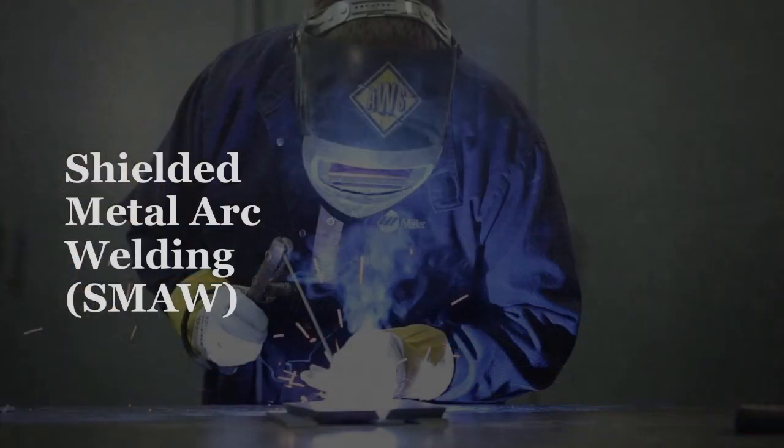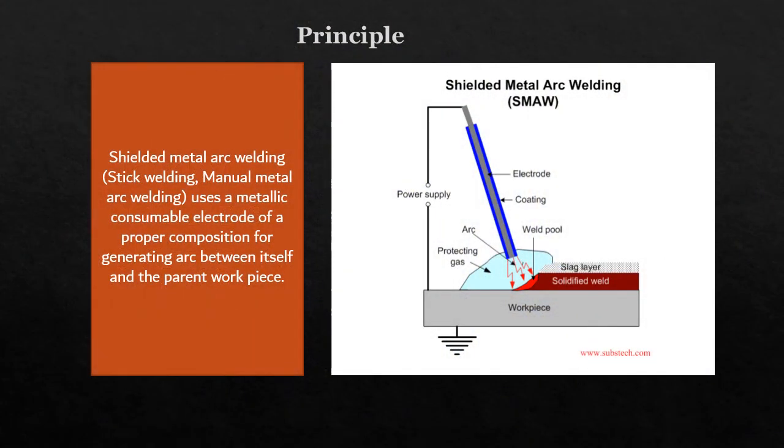For the last one, we have shielded metal arc welding, or we can call it SMAW. Shielded metal arc welding, or stick welding or manual metal arc welding, uses a metallic consumable electrode of a proper composition for generating an arc between itself and the parent workpiece. The molten electrode metal fills the weld gap and joins the workpieces.